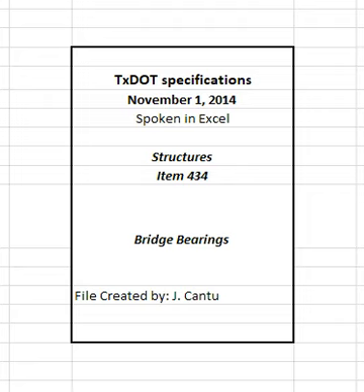Plain sample bearings must measure 9 inches x 19 inches x 1 inches. Laminated sample bearings must measure 9 inches x 14 inches x 1.5 inches with the following number of steel laminates: 50 durometer, 3 steel laminates; 60 durometer, 2 steel laminates; and 70 durometer, 2 steel laminates.